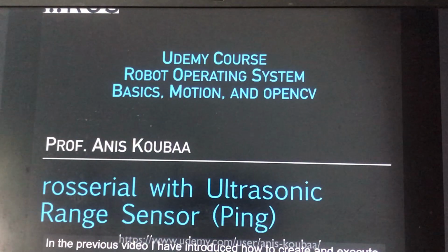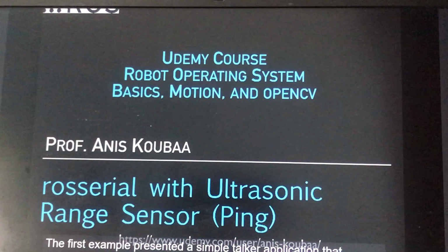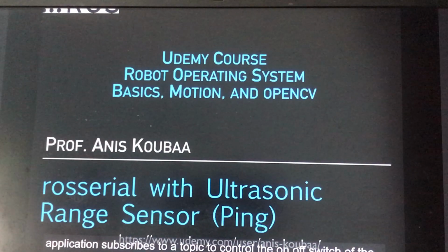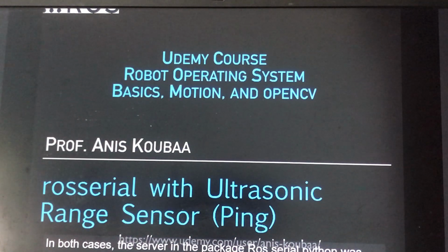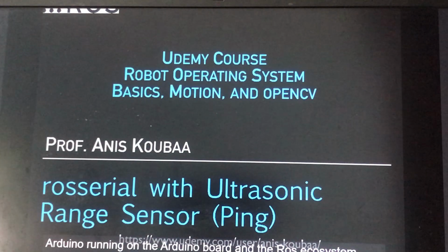In the previous video, I have introduced how to create and execute ROS nodes into an Arduino Uno board. The first example presented a simple talker application that publishes string messages, and the second application subscribes to a topic to control the on-off switch of the LED of the Arduino Uno board. In both cases, the server in the package ROS Serial Python was used as a bridge between ROS Serial Arduino running on the Arduino board and the ROS ecosystem running on the workstation.